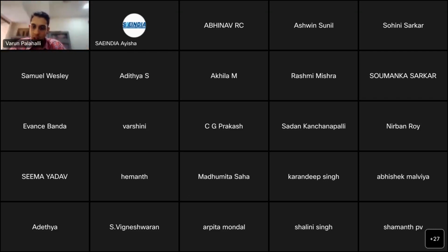Okay. So we have Sony asking a question. Is there any other advantage to defeaturing non-load bearing members apart from ease of simulation? Good question. What is the advantage of this? If your component is not bearing a load, there is absolutely no use for modeling it. So you are going to reduce the number of elements used as well. Your computational time is going to reduce, and computational effort is going to reduce. That is one.